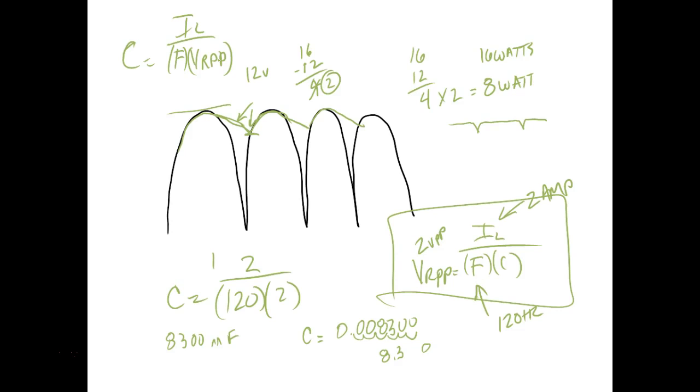And you're trying to get wire back there, and what's going to happen? Your wire is going to cause a voltage drop. So they put big filter capacitors back there, and they pay $100, $150 for those capacitors because they have to be so big. They have to handle 1,000 watts of power between those pulses. People run power cables all the way back to their trunk, and it has to be big gauge wire, but you can't use extremely big gauge wire because you still have to get it back to your trunk. So they use filter capacitors.